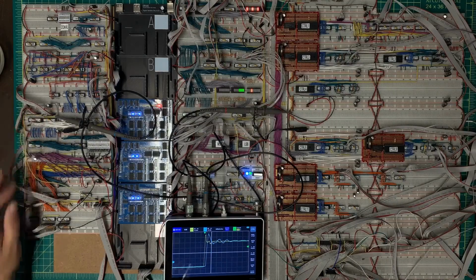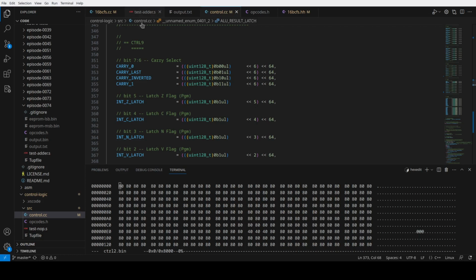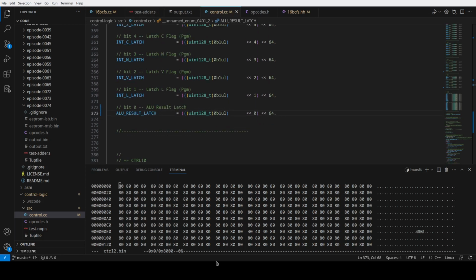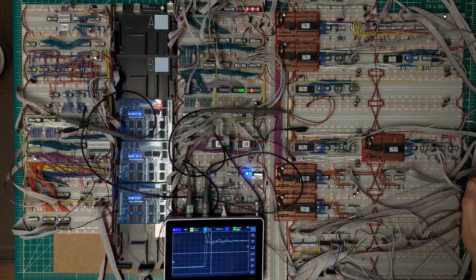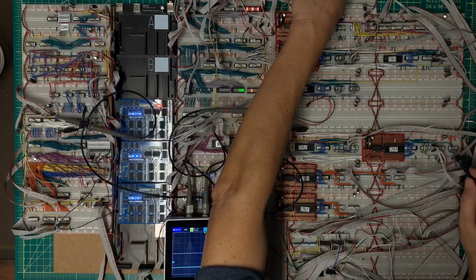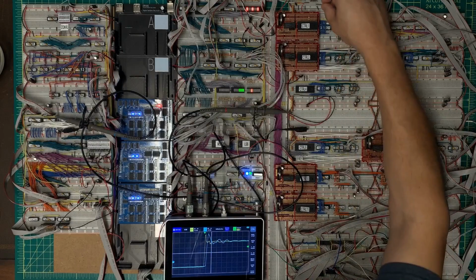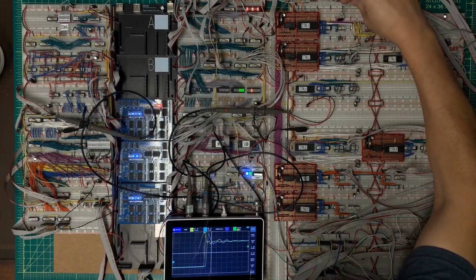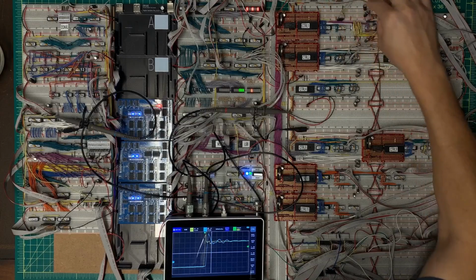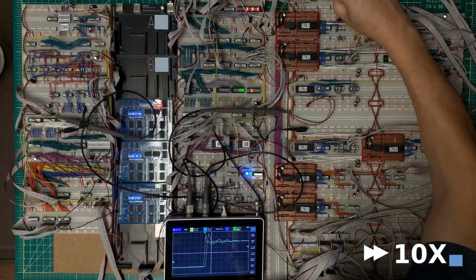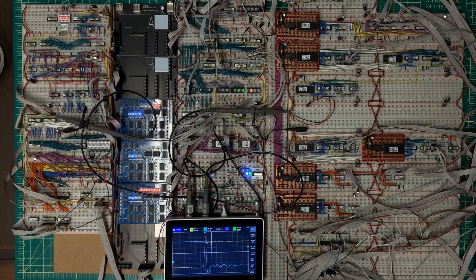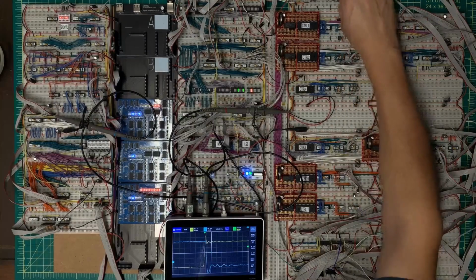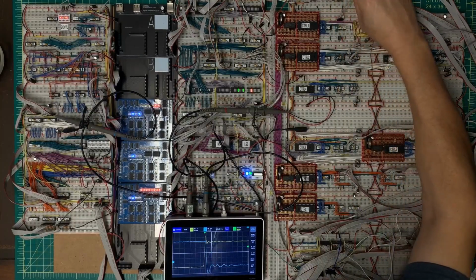All right, let's trace that signal. That's control ROM 9, and that is the least significant bit on there. That is NANDed with this clock, which probably should be an inverted version, so I'm going to move it over 1. Let's try that again. That's the problem I'm having. So now that it's inverted, it's latching at half clock cycle.